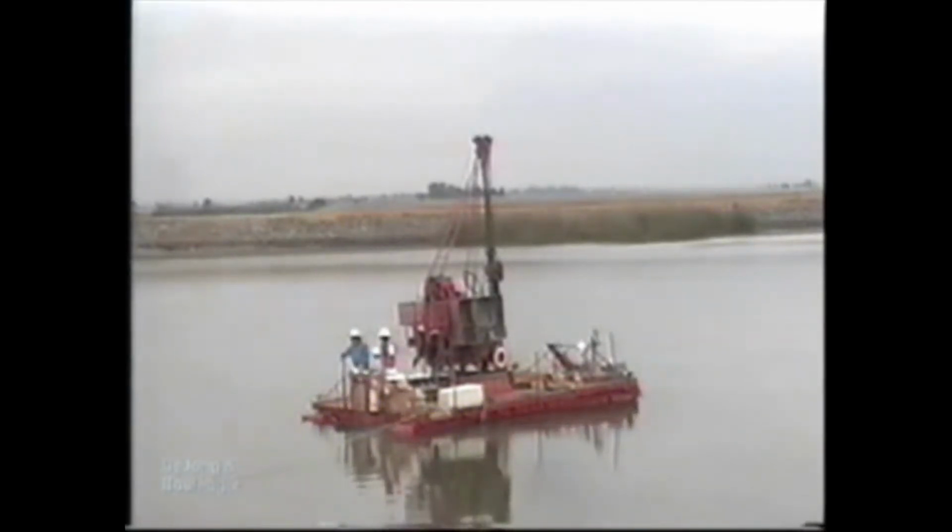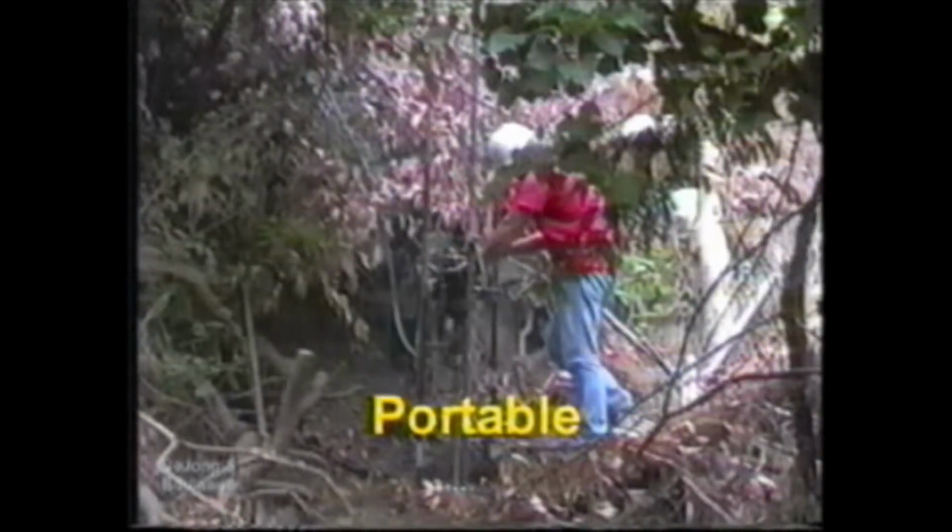Some overwater rigs consist of a customized barge, where the drill rig is positioned in the center and drilling takes place through a hole in the deck. Portable rigs can be partially machine operated, as shown here, or operated manually. These rigs typically have a depth limit of about 25 feet, depending on the subsurface conditions, and are used when access by an off-road rig is impossible and the expense of a helicopter is not justified.